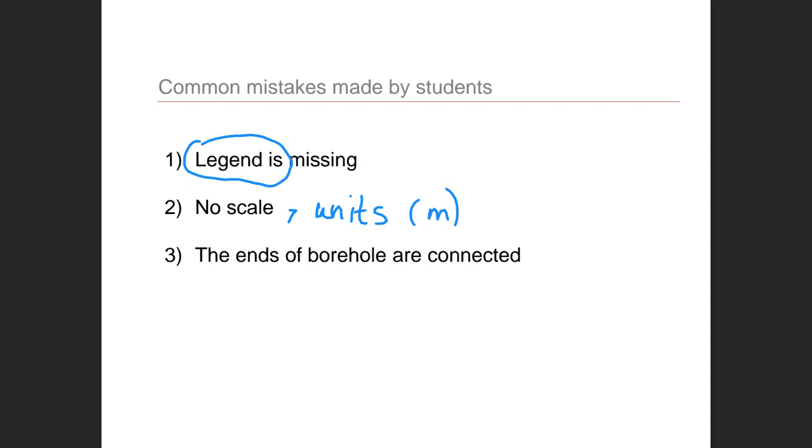How can we find out how far it goes rather than just assuming? We cannot really find out unless we drill the borehole deeper. We can do more tests. We can do another test, a geophysics survey for example, or we can do an SPT test. But then again, we will just need to drill a borehole deeper.